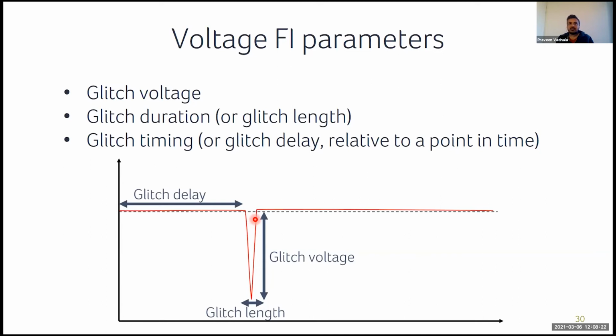It's not straightforward to know where exactly it is, for several reasons. So you want to have a proper point in the program where you know exactly where you are. This could be a UART output, this could be a flash read, something that happens all the time at the very precise moment.